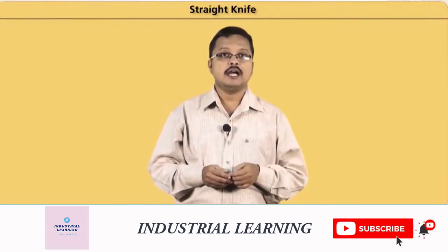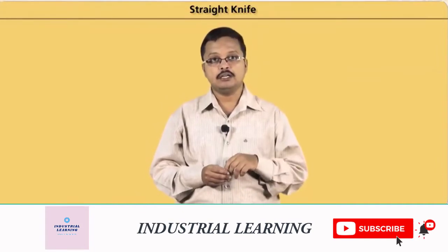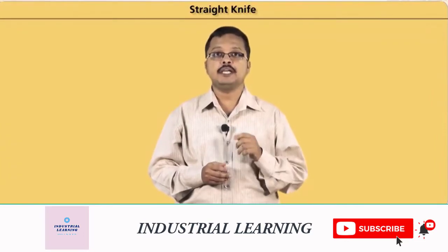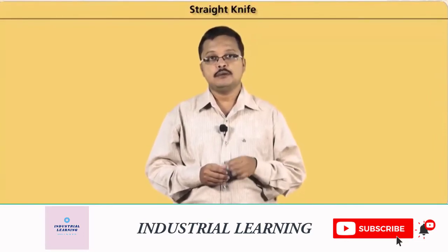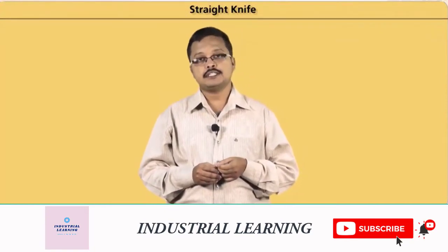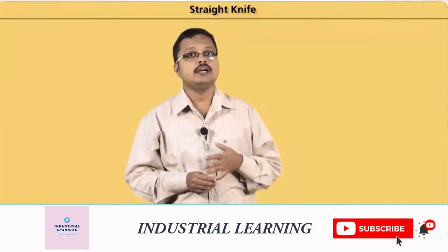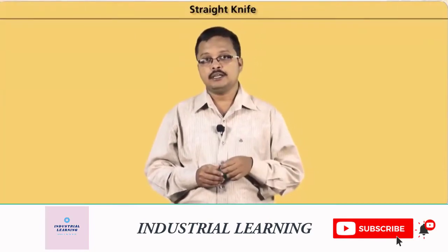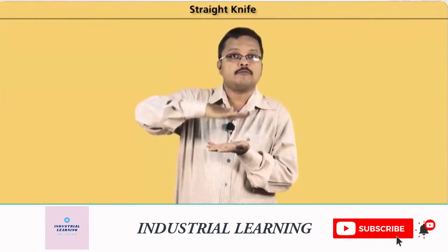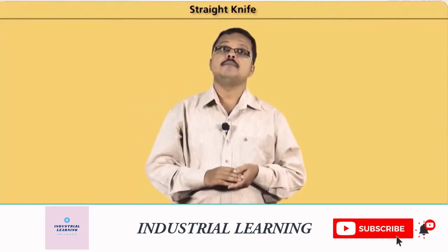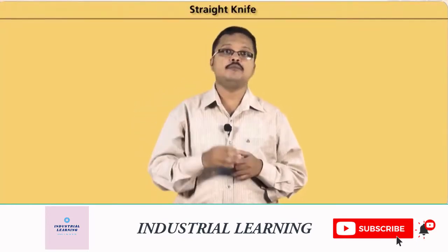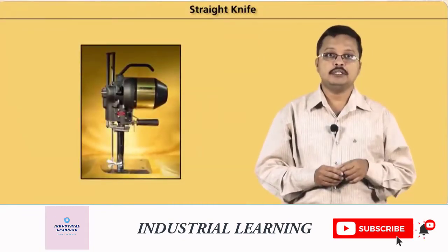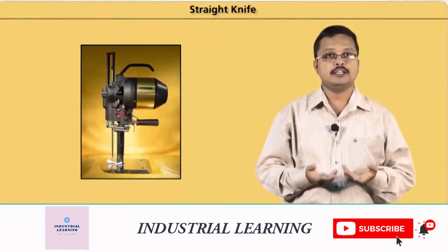Blade length and the adjustable height of the blade guard are factors determining the spread height that can be cut. This feature must be considered in choosing a straight knife cutting machine. The blade guard not only acts as a safety device for the operator, but also holds the top plies of the fabric, thus preventing them from lifting up during cutting. Metal mesh gloves are also available as a safety device for the cutting operators.